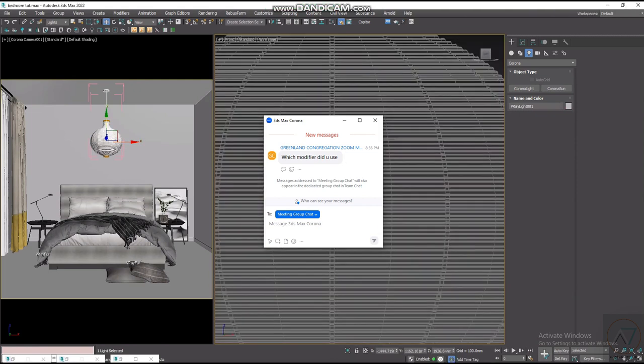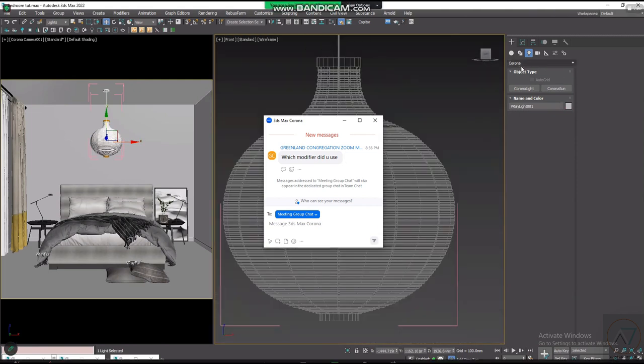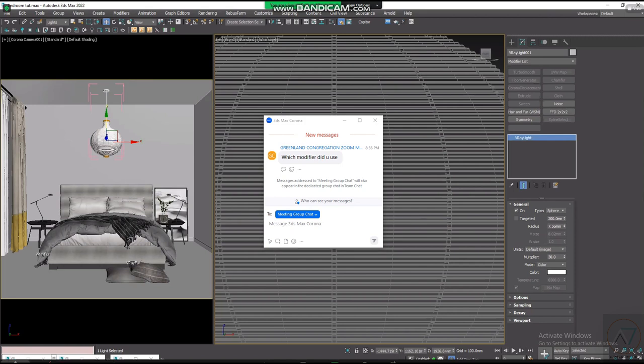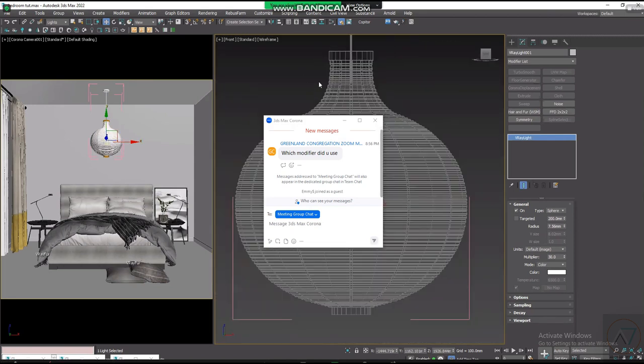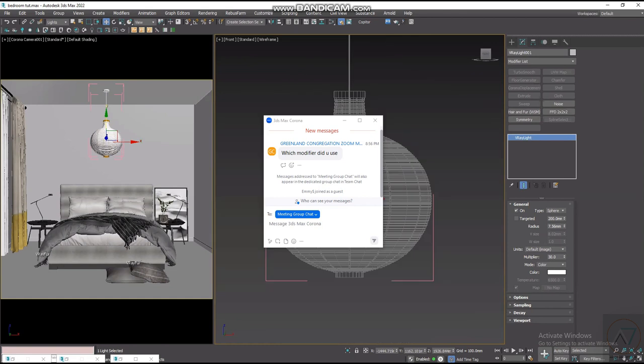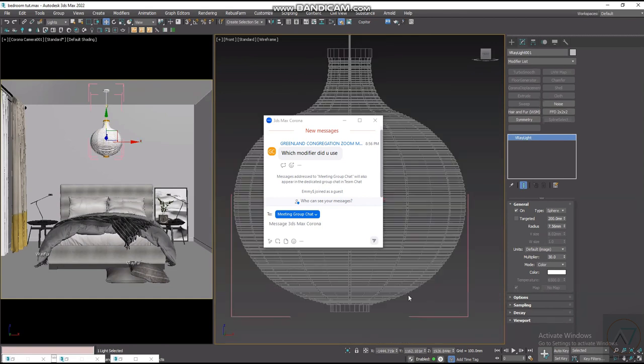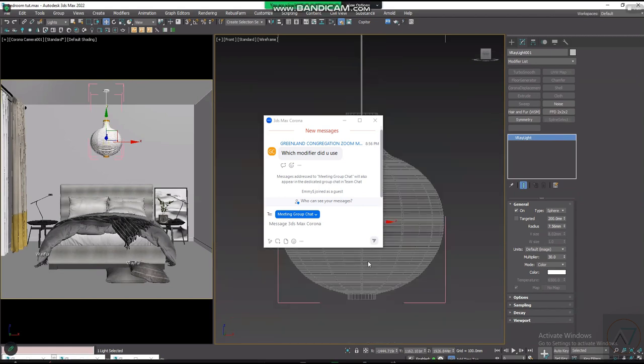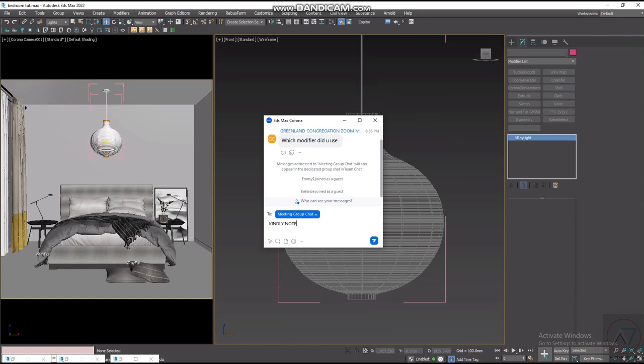So now this light here, okay, it has converted the light to a Corona light. So maybe I'll just leave the light, because if I come to modify, it's still a V-Ray light though. So let me just leave the light because there's no time. But for you to change it, or should I just delete? For you to change it, a quick way I do it is, okay, I look for the height of where the light is. You can see the height of the light is around 1926. Like so, I'll be able to position the new light I want to draw exactly at this spot. 1926. I just click on this, Control A, Control C, copy, then delete this light, delete.